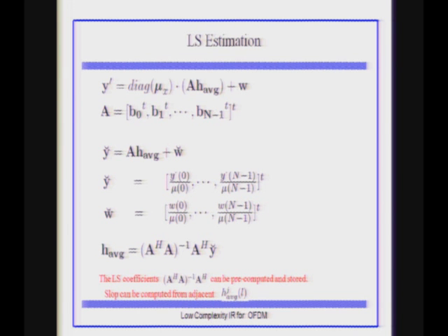So this works over several OFDM symbols too, so that you can compute the alphas. Yes, you need two consecutive OFDM symbols to compute the alpha. So there is a delay. But your BCJR works over a few OFDM symbols too. Correct. So do you work on this set of OFDM symbols, spit out the results, and then keep your H for the next future channel estimation, or do you just work on the whole block?